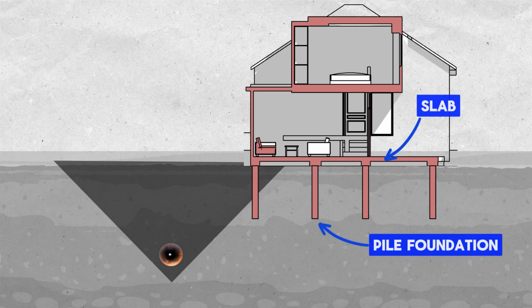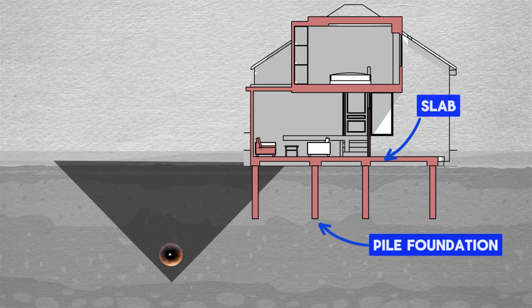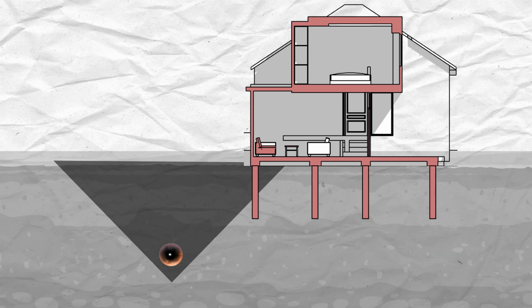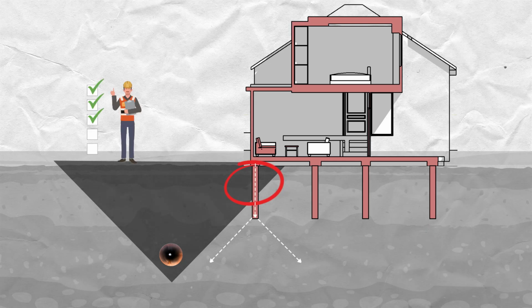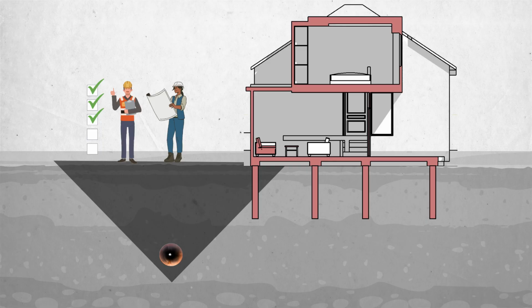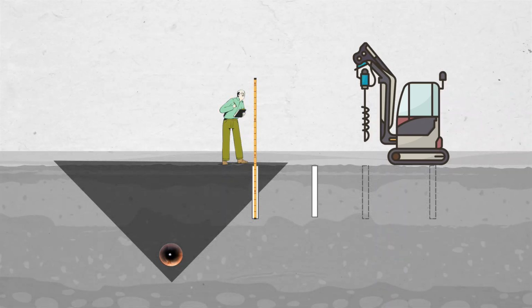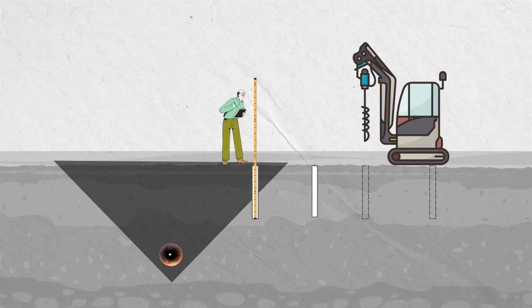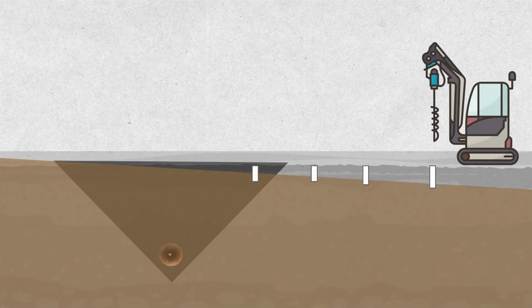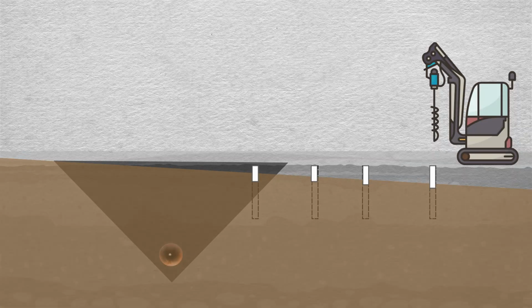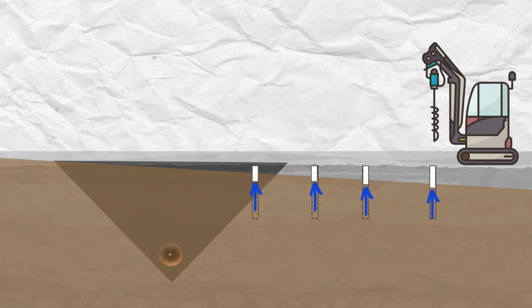This design proposes a slab on piled foundation, which requires deeper footings to support the weight of the slab, and they would pass through and below the zone of influence. The Water Services Coordinator will need to see the plans and sections of this foundation design, demonstrating that the pipe is not impacted before approving the building plan. During construction, the Water Services Coordinator will need to witness the actual depth of the piles as they are constructed to validate that the piles were indeed driven to the intended depth. Often, pile depths will change during construction because rock and stiffer material is encountered, providing sufficient bearing capacity, and the geotechnical engineer is able to approve a more shallow footing that can save a lot of money.